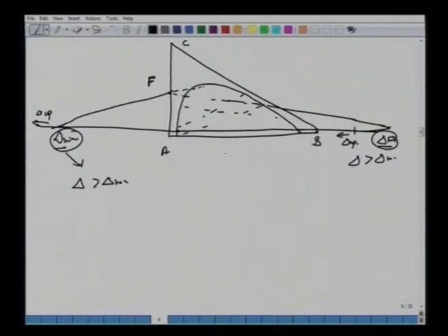And we said that it all depends upon the slope of these tie lines. In some cases extract equilibrium composition is greater than the raffinate, so we have an upward slope. In some cases we have extract compositions smaller than the raffinate, so we have the downward slope like this, and del min can move from the left and the right hand side.